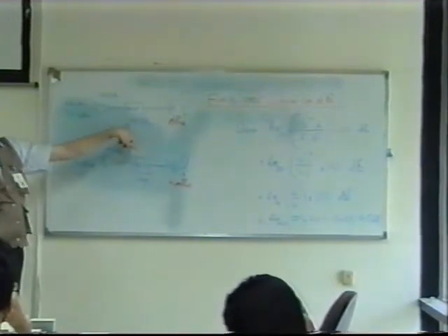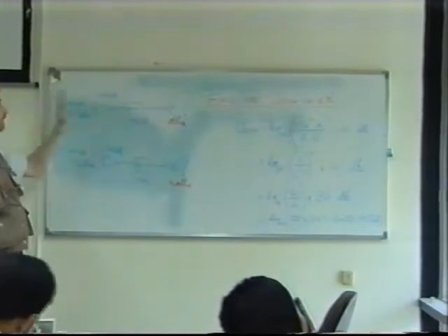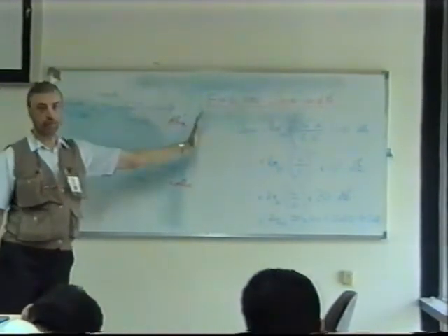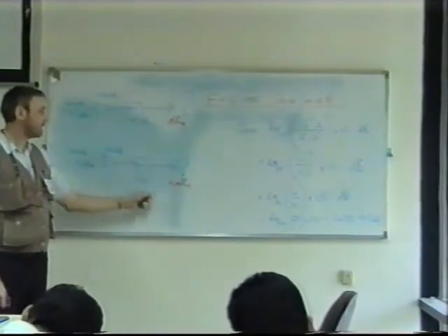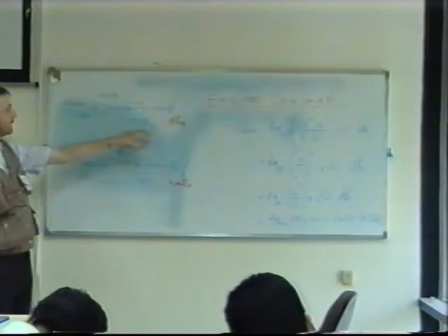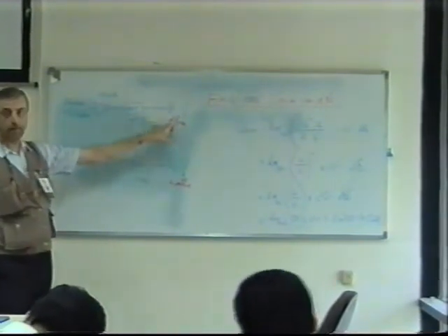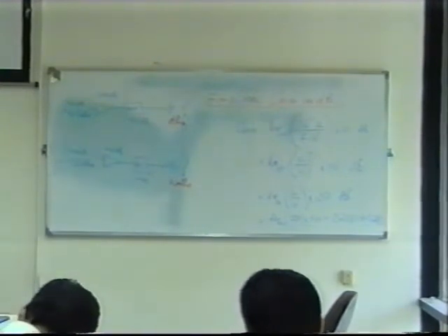Yes, 100 dB gain, and the attenuator, that's an attenuator. So now it's a minus dB, you see. So we're amplifying it, then we're attenuating it, then we end up with a result. And same here, we amplify it, attenuate it, we get a result. The only difference between the two questions is here I want the output power in dBm, here the output power in watts, or milliwatts, or whatever it is.